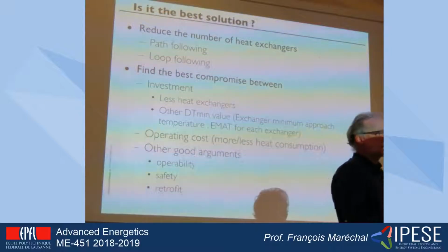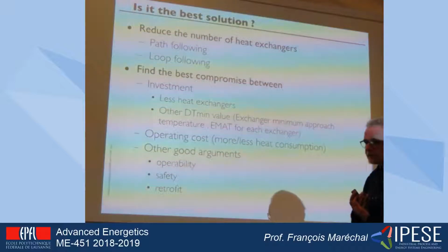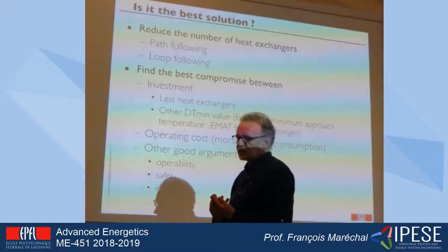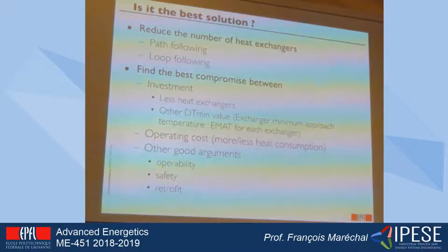there is no way to reduce the number of heat exchangers, and perhaps the remark of having a very small heat exchanger is perhaps not the best idea, and removing one heat exchanger could perhaps save a lot of money in investment without penalizing too much in the operating costs. Okay, so the idea would be then to see if we are able to alter or change the design in such a way that we will reduce the total costs.